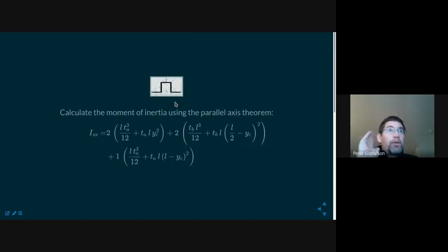Now, since we've talked about that, I want to recognize that you can still use this theory even if TA over 3L is not really small. If it was 10%, is that small enough? Well, you can do the calculation just like I've done it, and you'd get an answer. The thicker it becomes, the more error creeps in. If it's very thin, the error is trivially small.